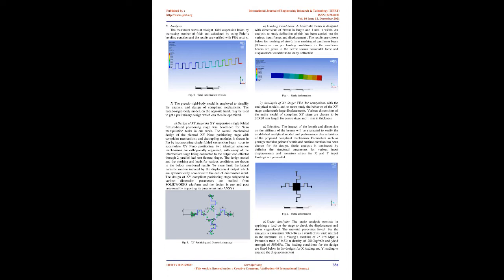The above deformation and von Mises stress and various force reactions are obtained from analytical and FEM methods. A. Modeling. The design considerations of the pantograph compliant mechanism are presented with its benefits. Also, displacement synthesis is carried out for selected folded beams. The configuration of the mechanism, its size and sectional details have to be evaluated analytically and are required to be verified using the FEA tool. The design of the folded flexural hinge is proposed on the basis of results obtained earlier, and design of experiments is used to promote the straight suspension flexural hinge.